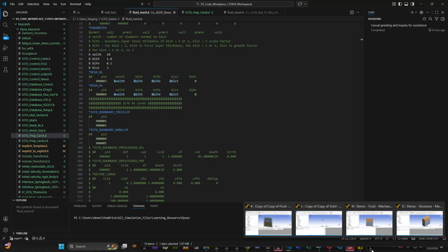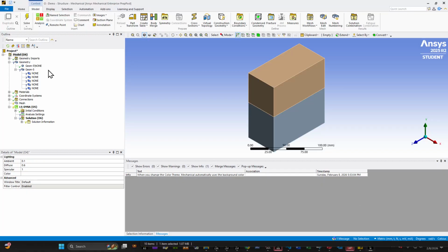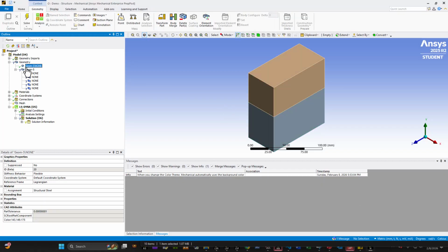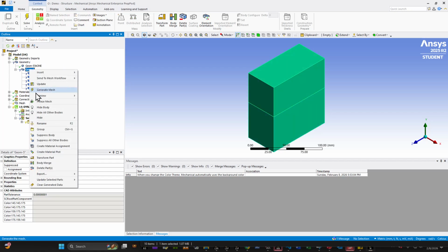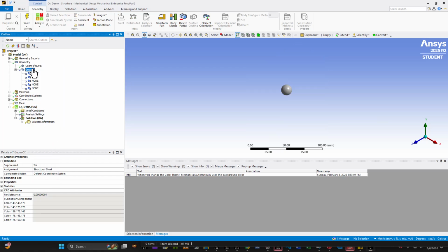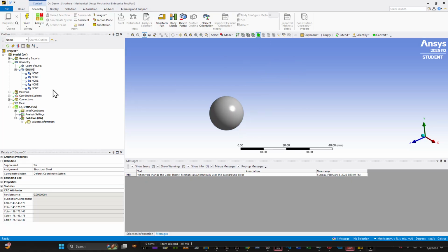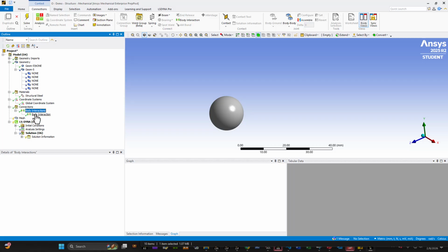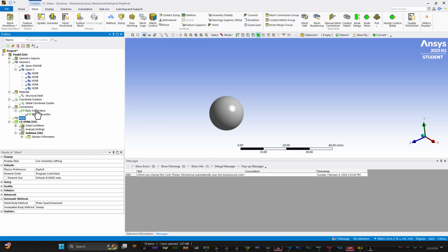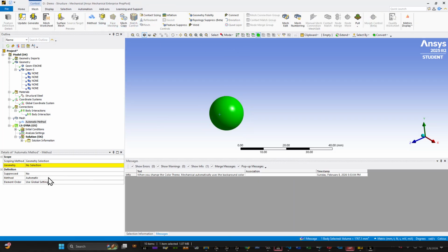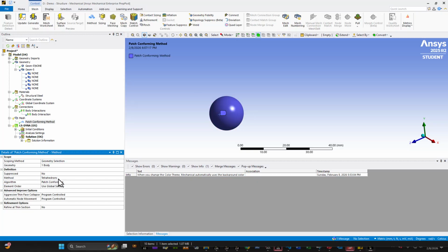Okay. All right, so let's look at the FEA side, right? On the FEA side, I'm going to suppress all the CFD stuff to start. And all I have is a ball, right? Would you like to guess how easy it is for me to generate the mesh I wanted? So I can suppress this, and I'm going to put a method here. Remember, I just want this thing to be a tetrahedron, just for simplicity reasons, right?